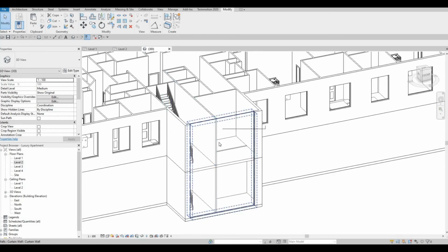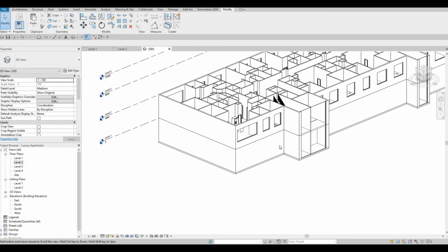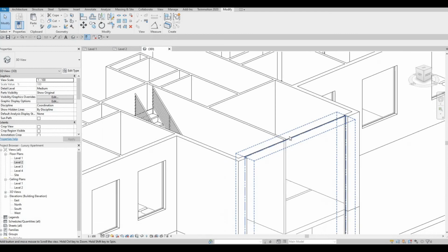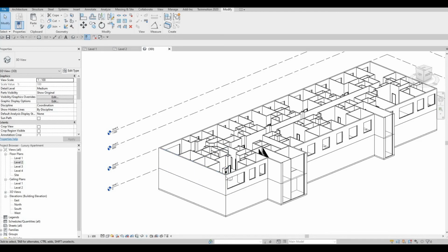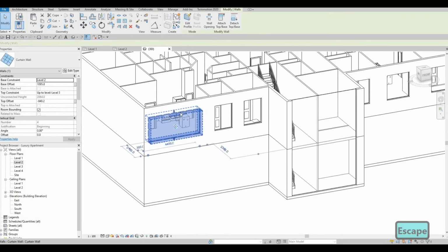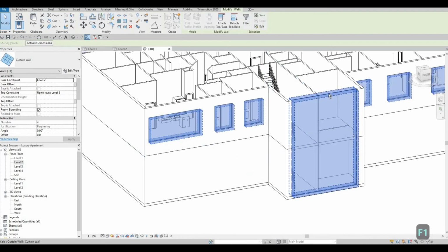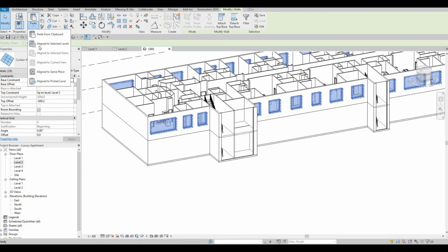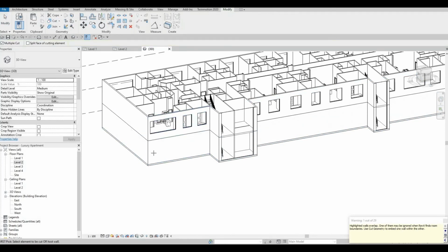We need to be mindful on this spot because once we create or copy the floor plan, we need to remove this because it will create an error once we add multiple levels to our level 3 and 4. So now what we could do is we could copy. So I'm going to select and then deselect this by holding on shift and selecting that again. I'm going to copy and then paste to selected level. So level 1. Now we just need to cut geometry again.